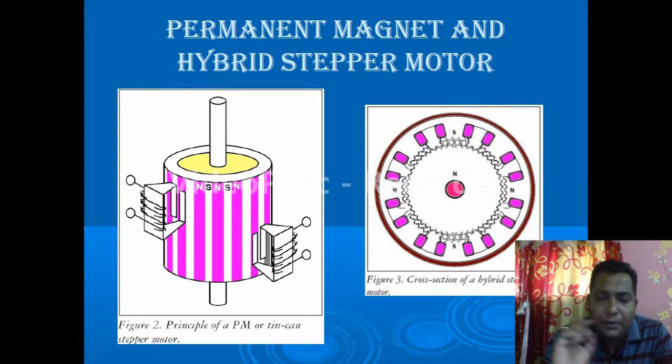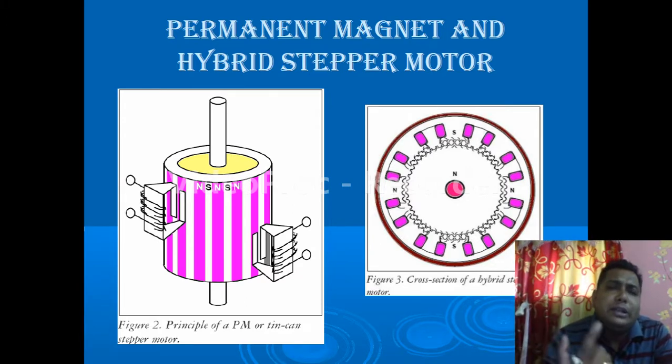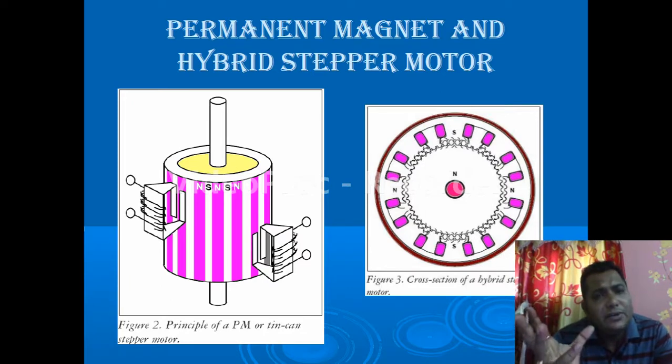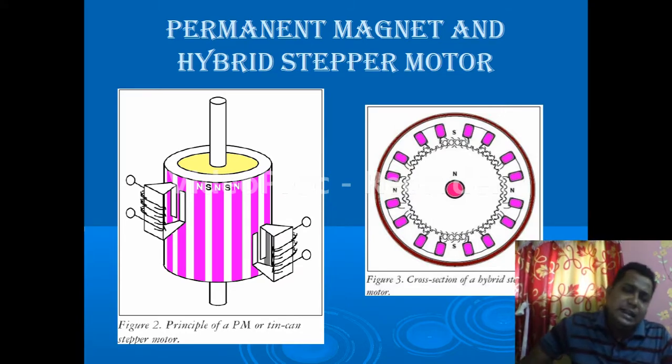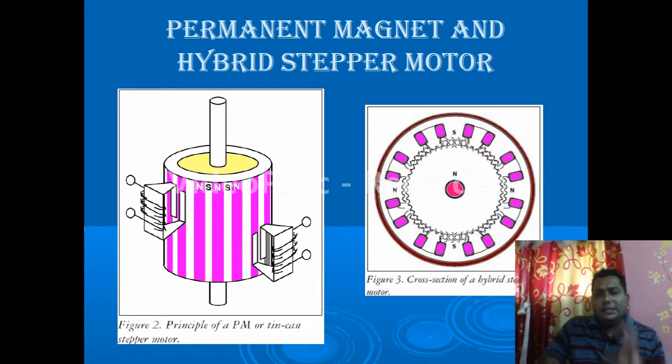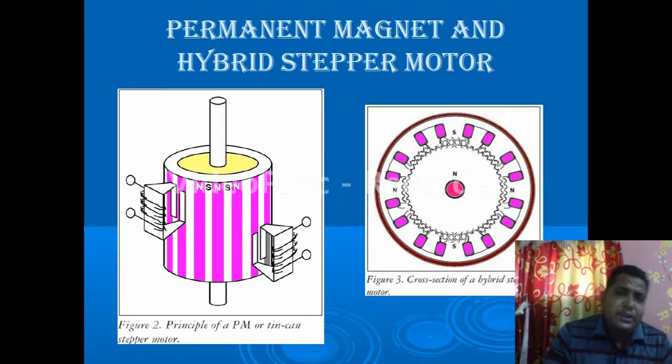Over the periphery of the rotor, there is the stator section. So on the outer side there is the stator section, inside that we have the rotor section, and in the rotor all the alternate poles are there, north south. This rotor section is a permanent magnet, and on the outer side of this machine, the stator section, we have the slots, and there we will give electrical input.